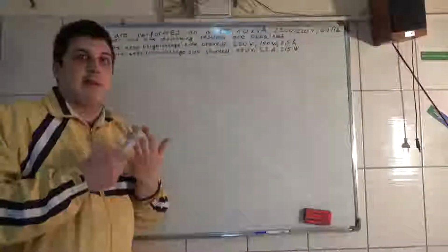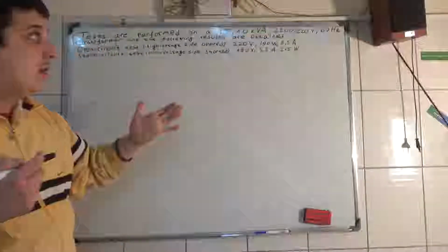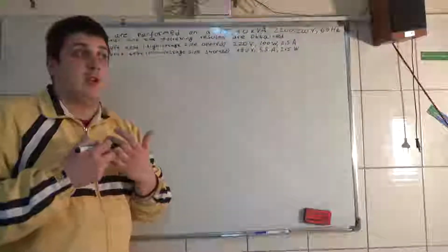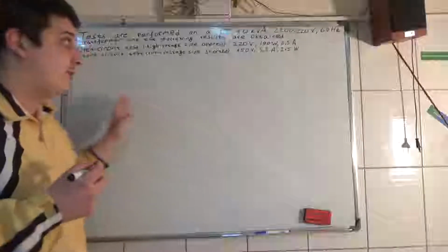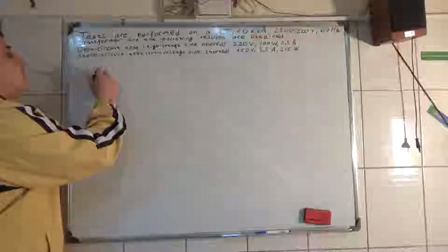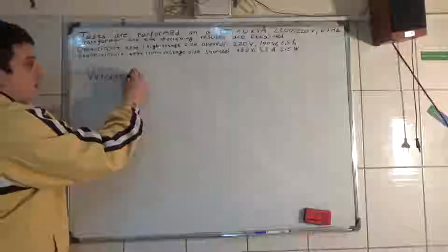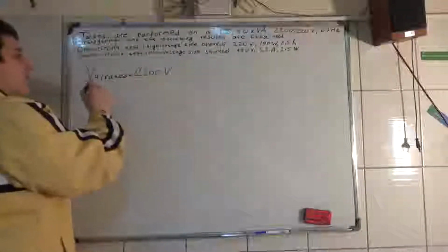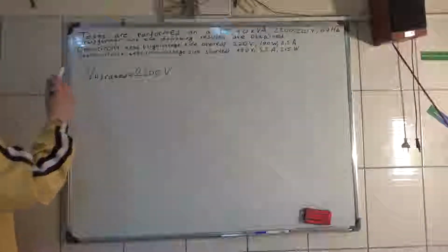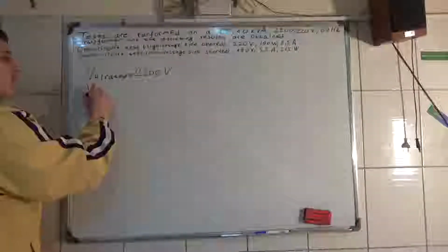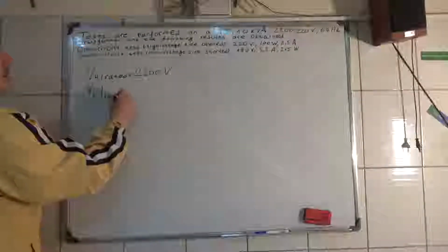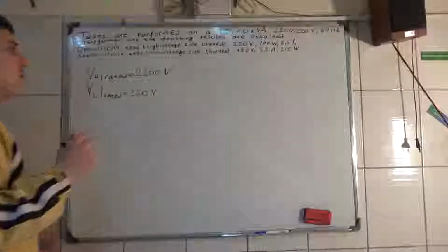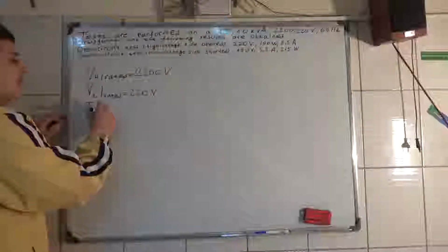Now we know that it has 10 kilovolt ampere power. So what are the currents in there? The provided voltage, the rated voltage on the high voltage side, VH rated, is 2200 volts, where the subscript H represents high, and the rated low voltage side is 220 volts.